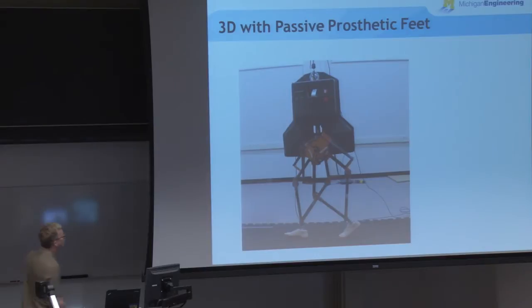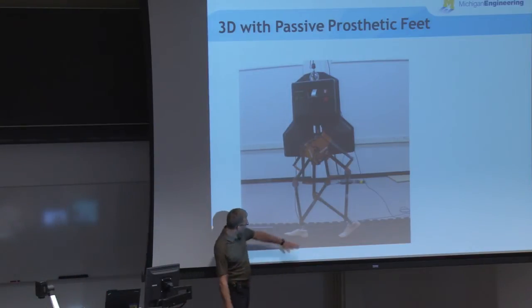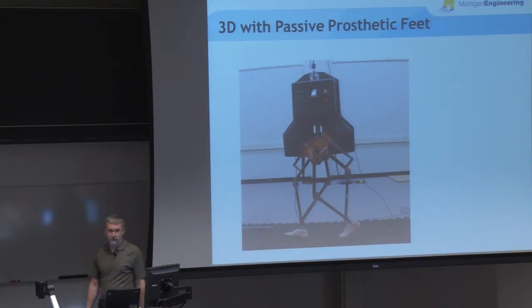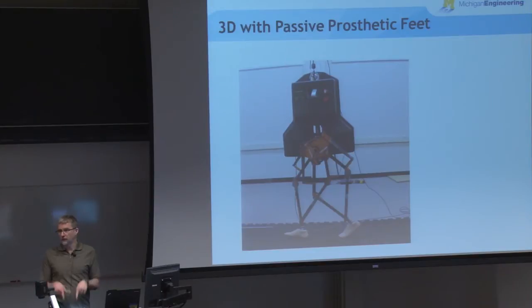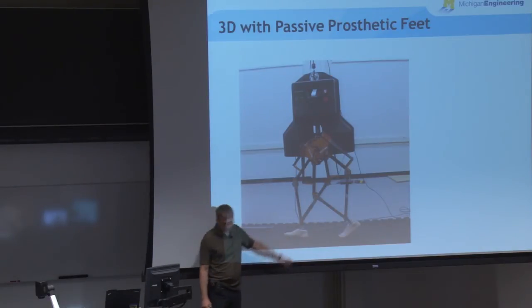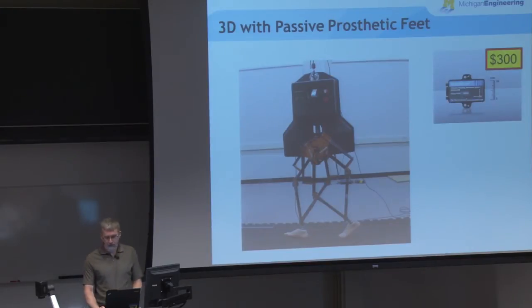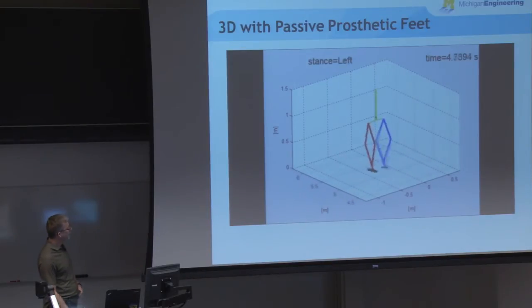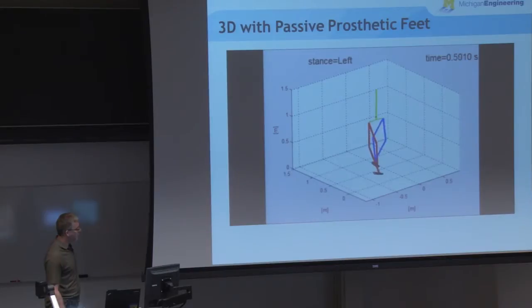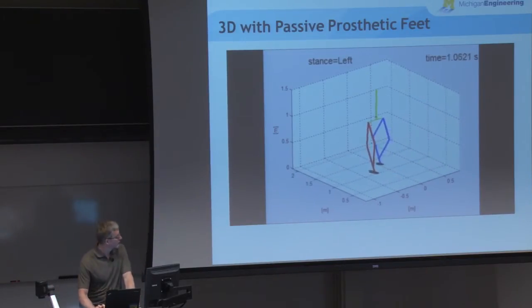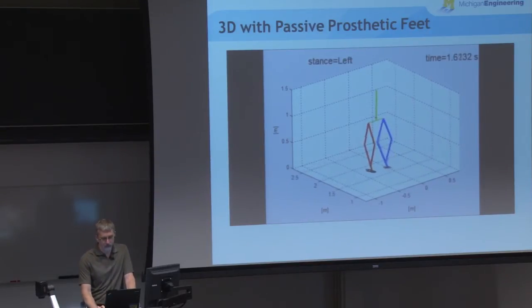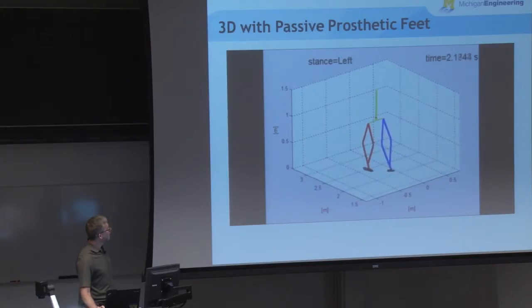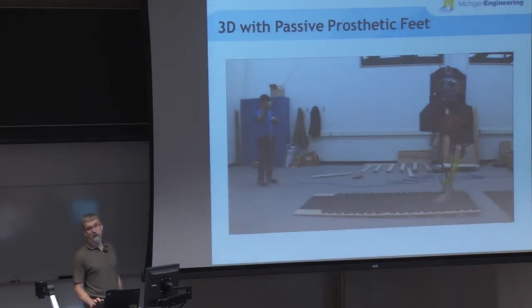Okay, so here's MARLO. That's the Michigan copy of the robot. We have put prosthetic feet on it simply because to initiate gaits, we want to start from a standing posture, and on point feet, that's hard. And with prosthetic feet, that's a little bit easier. So they're not actuated, they are passive. We've really splurged and have an expensive IMU on there. We've got our theory extended to work in 3D. We've done simulations with a compliant ground model that has stiction and slipping, etc. in it. Applies ground contact forces to the four corners of the feet or not, depending on how they are in contact. So we've checked out our theory. It's quite robust. And so then we've started experiments.